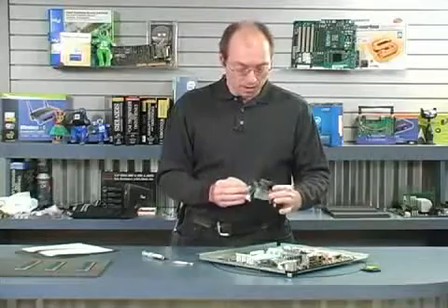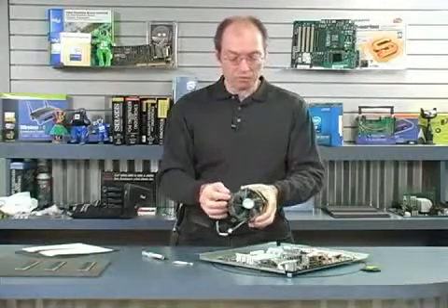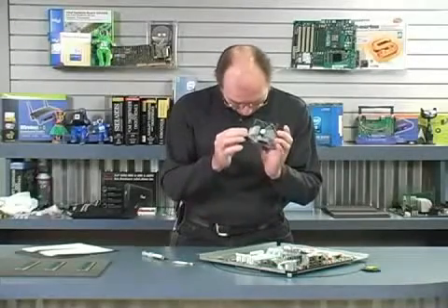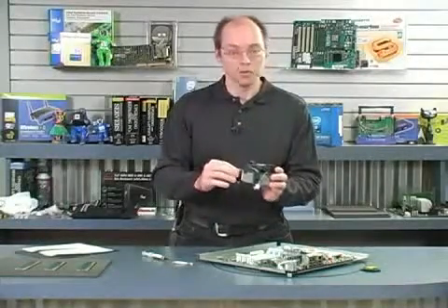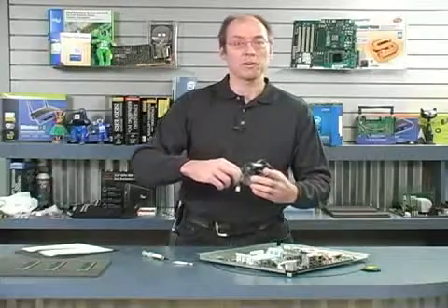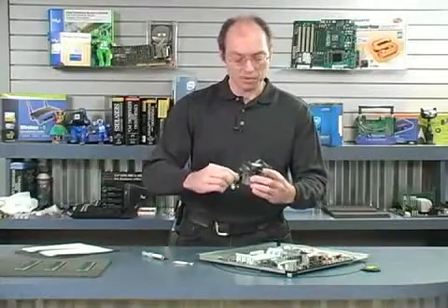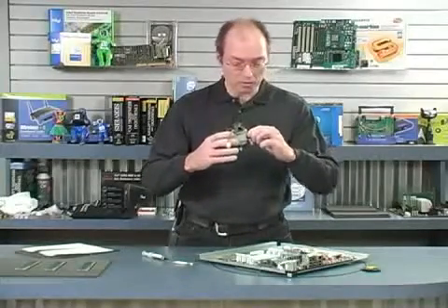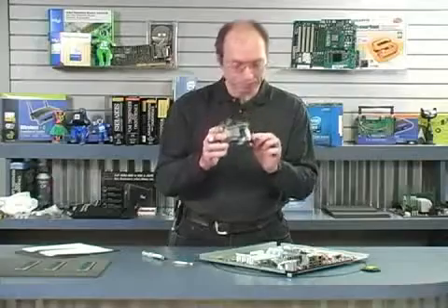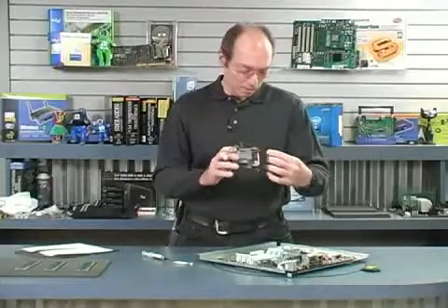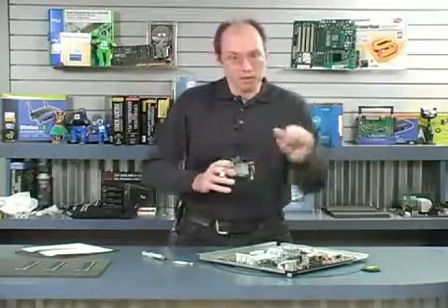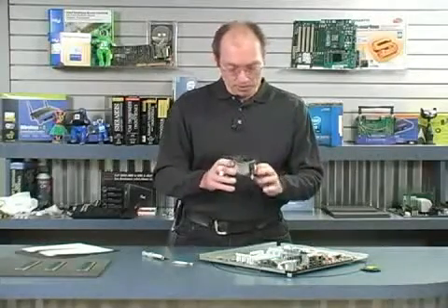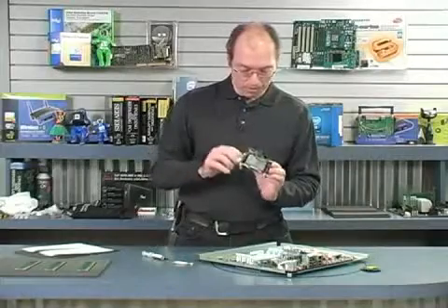Intel heat sinks are noted by these 4 push-pin retainers, and they have arrows on them. What's kind of funny is that when you install the heat sink, the knobs on top of these retainers have to be turned the opposite way of the arrow. So I'm making sure that all those are turned in the right direction. It's a common mistake that people see the arrow and think they have to turn it. That's actually for the removal of the heatsink. So make sure these are all with the proper orientation.